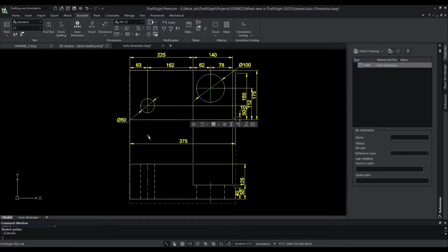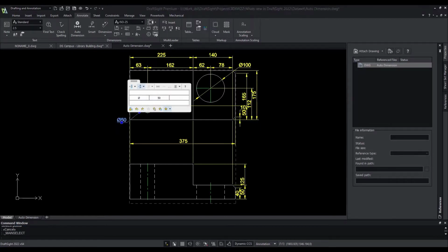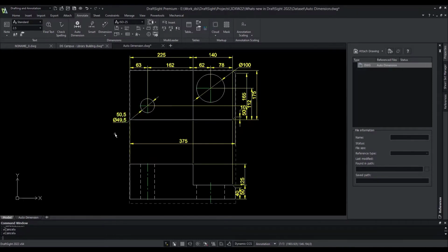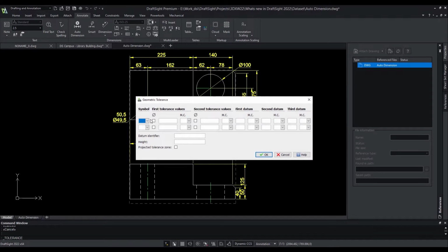On the other hand, the contextual menu is our workhorse, giving us an option to define limits, fits, precisions and many more when we try to modify a dimension. We can then save the settings in a favorite and utilize it as and when needed. We always need to keep some tolerances on a dimension, and tolerance functionality helps us to precisely define a geometry and make production ready drawings.